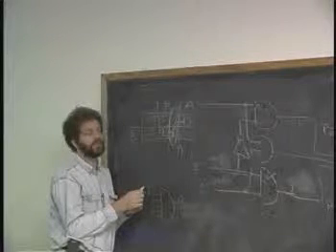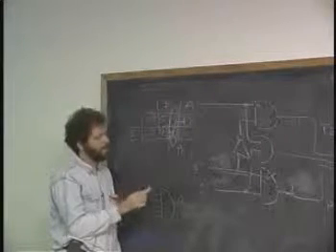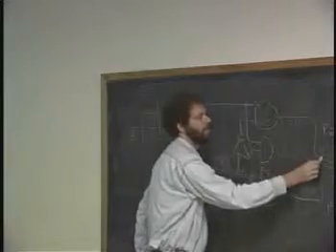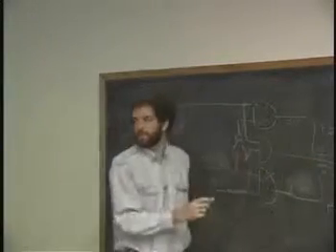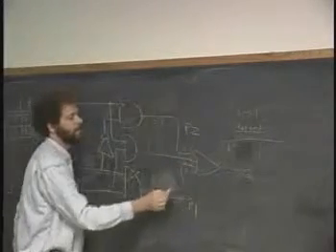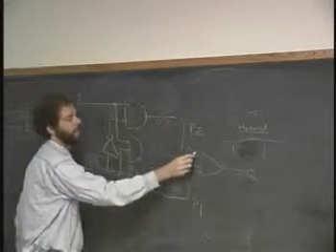It can't happen. The final gate's an OR gate, not an AND gate. The final one's an OR gate, but to start with, everything was 0. Correct? Because the output was 0. Correct. And to end up with, everything was 0, because the output's a 0. And I just got through proving to you that for each one of these guys, they didn't glitch.